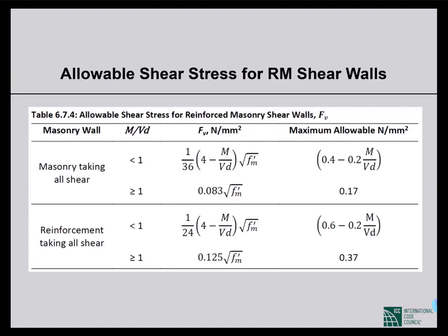Okay. For reinforced masonry, we can design in two ways. For tensile stresses, we always depend on reinforcement. But for shear stress, we can depend on masonry or we can depend on reinforcement. So depending on our assumption, the allowable stresses are different.